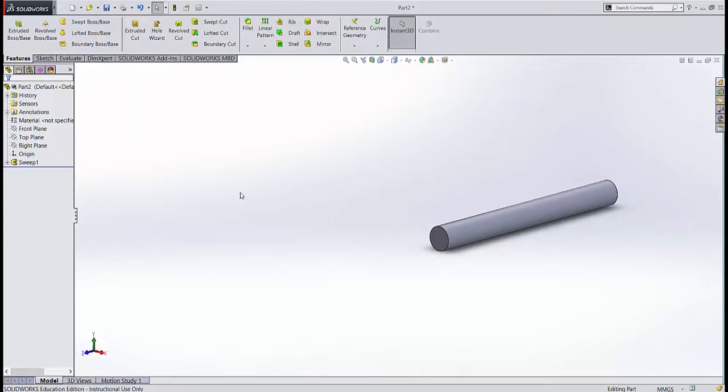You'll note that this is equivalent to an extrusion. In fact, extrusions are simple special cases of sweeps. Sweeps that have a straight path for the profile to be swept across are extrusions, and they're common enough that extrusions are provided as their own feature. Sweeps are more general and allow you to take the profile and sweep it through any sketch path that you define on one or more sketches.